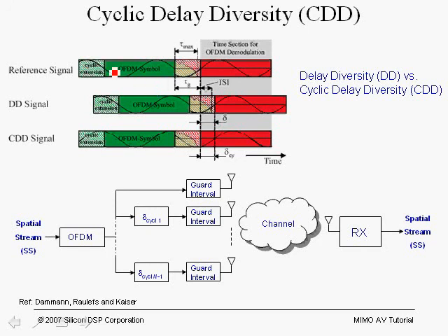Here we're showing one harmonic in the OFDM symbol, and notice that in an OFDM symbol the signal is continuous across the cyclic prefix into the OFDM symbol, and that has a lot to do with the way that an FFT can be formulated from a Fourier series. But we won't get into that, but it's very important to note that this is continuous.